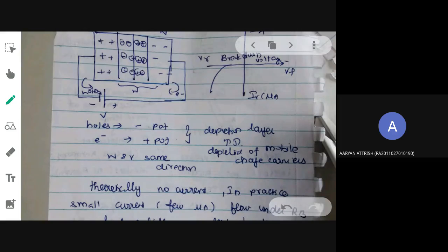Ideally there will be no current flow, but still there is light, still there is heat. So thermal generation of electrons and holes will happen, and these thermally generated electrons and holes will hit the covalent bonds. When these covalent bonds are hit, they will release extra holes and electrons, which again hit other covalent bonds. So this action will happen in a chain, resulting in what is the name of the breakdown?